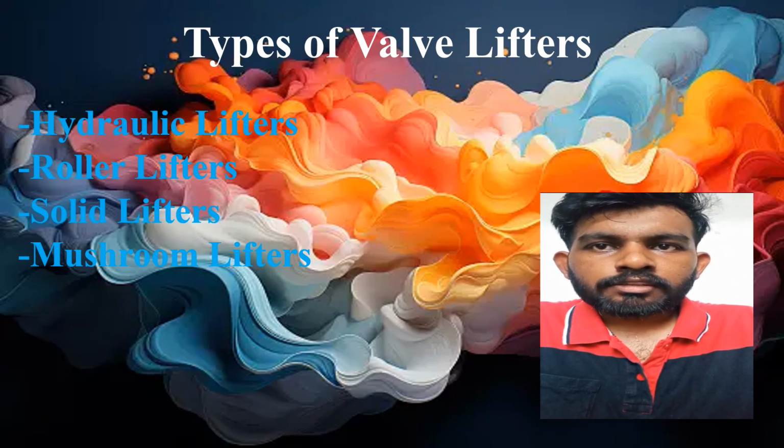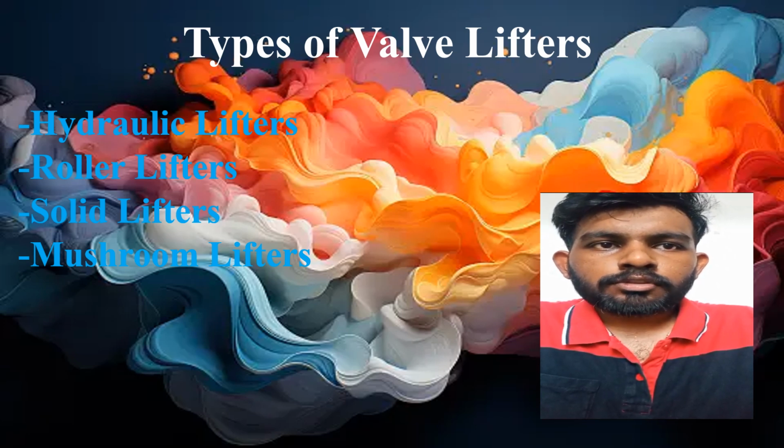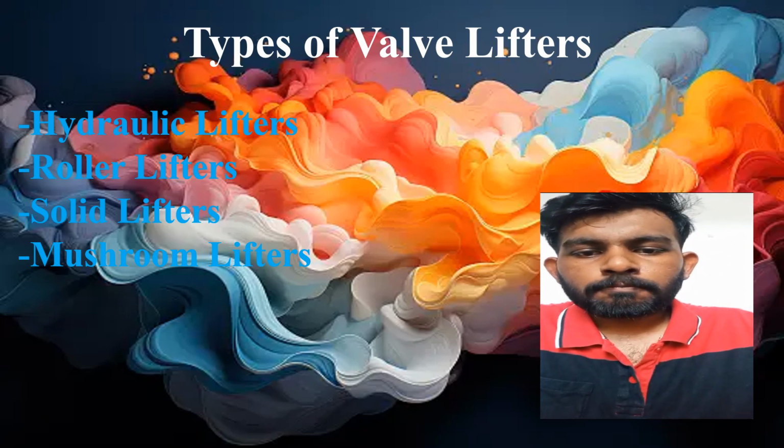The last one is mushroom lifter. Mushroom lifter, also known as a flat face lifter, has a mushroom shaped top surface instead of a round plunger. They are commonly used in older engine designs and can be either hydraulic or solid.